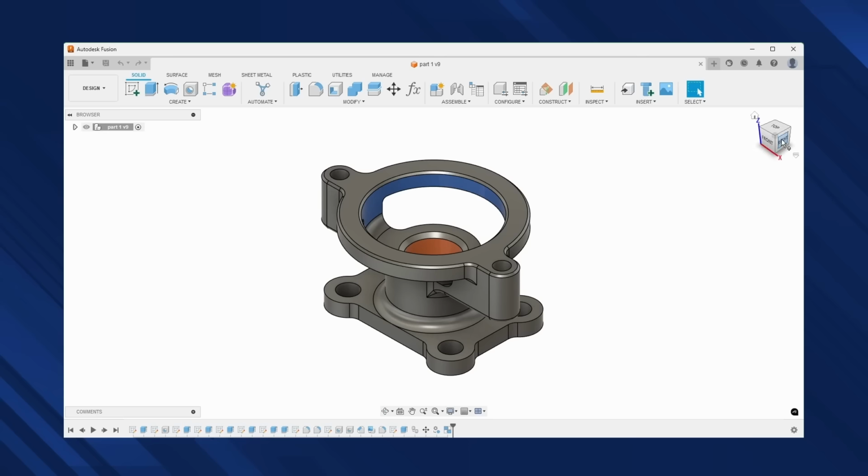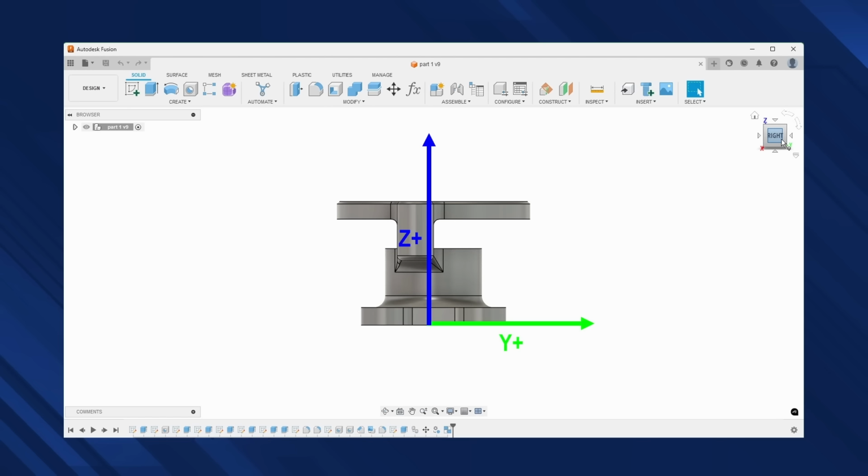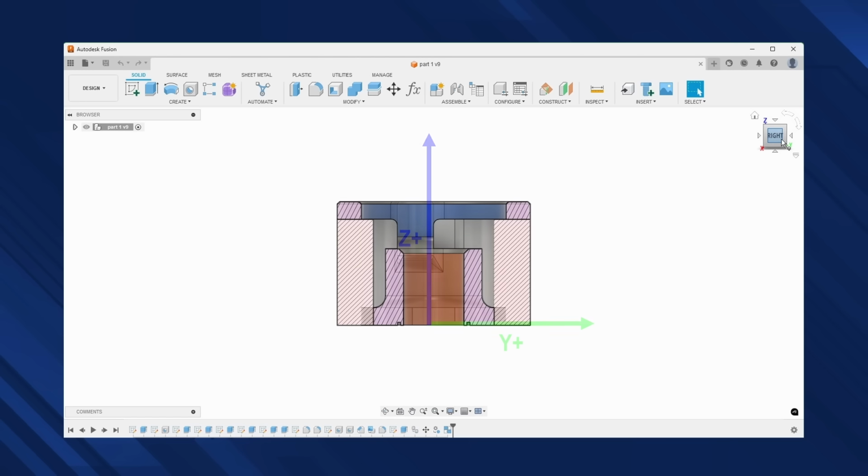As we consider our fixturing options, it's important to anticipate challenges and come up with solutions in parallel. For instance, if I orient the part in this way in Op2, what will be happening to the unsupported feature as I machine the excess material from the top? How will this specific material type react? What are the tolerances on the feature? Do I need to consider support material when designing my fixture?